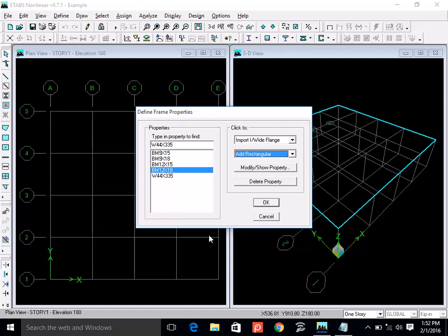But generally, because 9 inches is too small to accommodate steel bars and to do the compaction. You know, when you are casting a column, say it is 12 feet high column, you have to insert the vibrator inside the column. So 9 inches, it's too small. Generally, people don't do that.